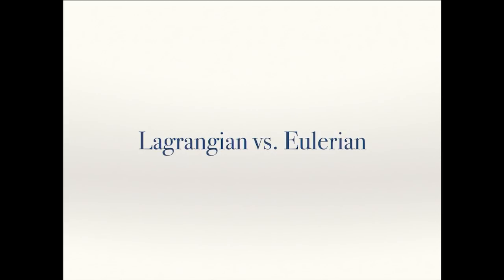Question for Adam. You mentioned the co-rotated strain tensor. You had a matrix Q in there. I was just wondering if you could talk a little bit more about where that comes from. Sure. That's just the polar decomposition of F. So we take F, we do a polar decomposition, which breaks out your matrix into a rotational matrix and a scale-shear, so a symmetric matrix. When you break out that rotation and then basically discard it, you're explicitly saying that your strain metric is no longer sensitive to rotations.